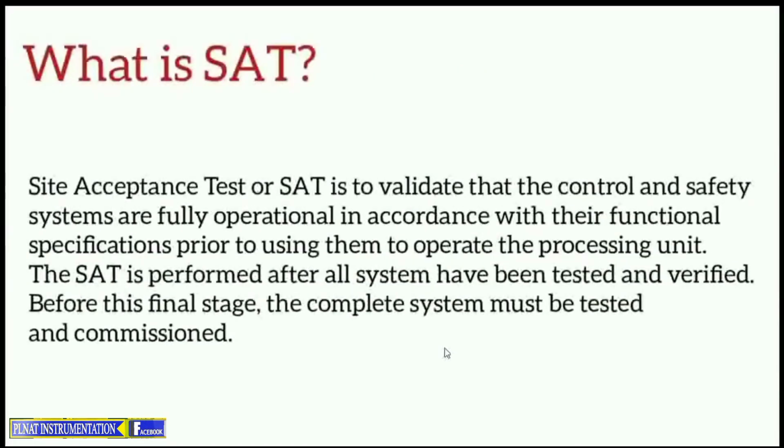What is SAT? Site Acceptance Test or SAT is to validate that the control and safety systems are fully operational in accordance with their functional specification prior to using them to operate the processing unit. The SAT is performed after all systems have been tested and verified. Before this final stage, the complete system must be tested and commissioned.